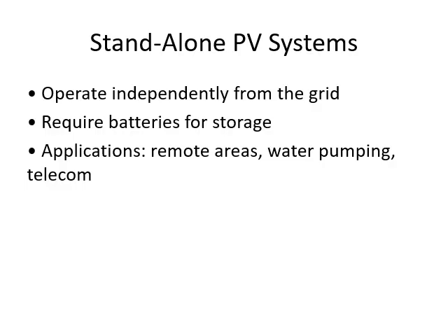Some more details about the stand-alone PV system. It operates independently from the grid and requires batteries for storage. Okay, and you can apply it in remote areas where the central power distribution system is not there. It can be used in water pumping in farms, or it can be used on the sea if you have to do any pumping there, or any electric supply is needed, you can just install the solar panel there, right? And also telecom towers, right? Telecom towers are usually established in places where no one goes regularly and there is no electricity supply. So there you can set up this stand-alone photovoltaic system.